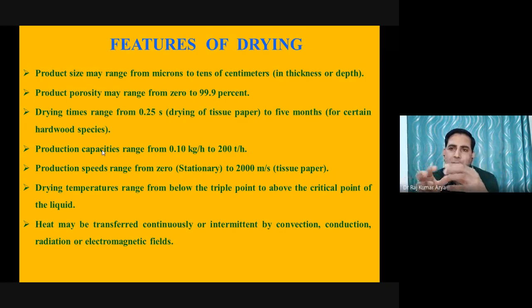By chance, you may have a very high temperature on the outside and a very large amount of moisture inside. If you do not match the rate of evaporation of the solvent from the surface and the diffusion of solvent within the material itself, be it food material or wood, you will find cracks there. And then porosity also needs to be controlled.